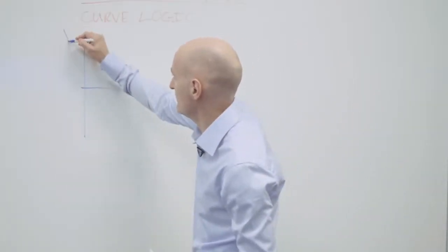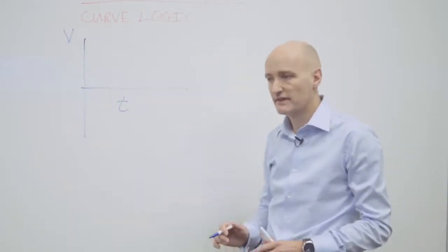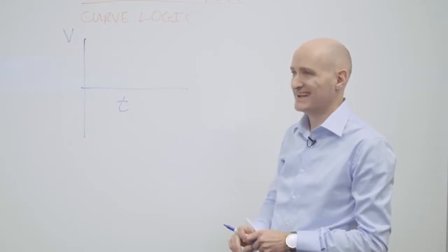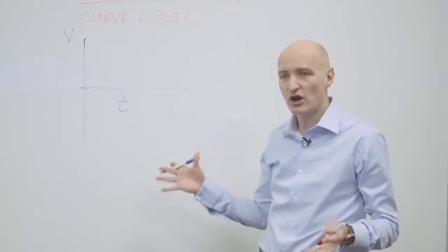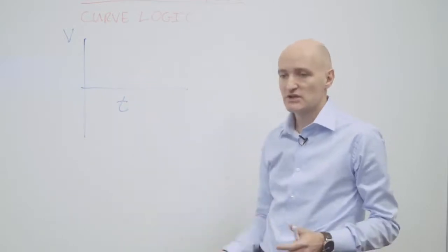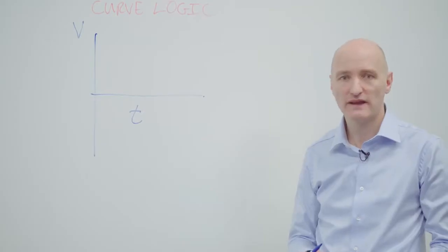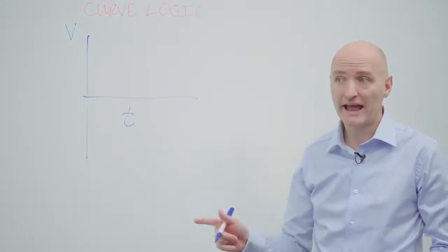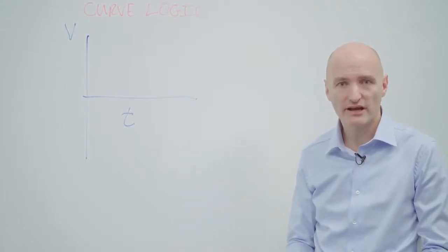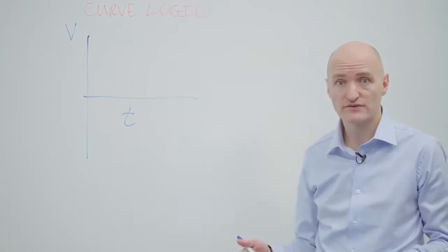So this is the voltage of the battery, and this is time. And this is kind of key, because we can tell an awful lot about what's happening in the electrical system in your vehicle based on this signature. Our large fleets tell us that 80% of the failures that happen in large fleets are caused because of the electrical system. That means if I'm a vehicle out on the road, my starter motor doesn't work, my battery runs flat because the battery's dying, or my alternator's not working. 80% of the failures are caused because of one of those three things.